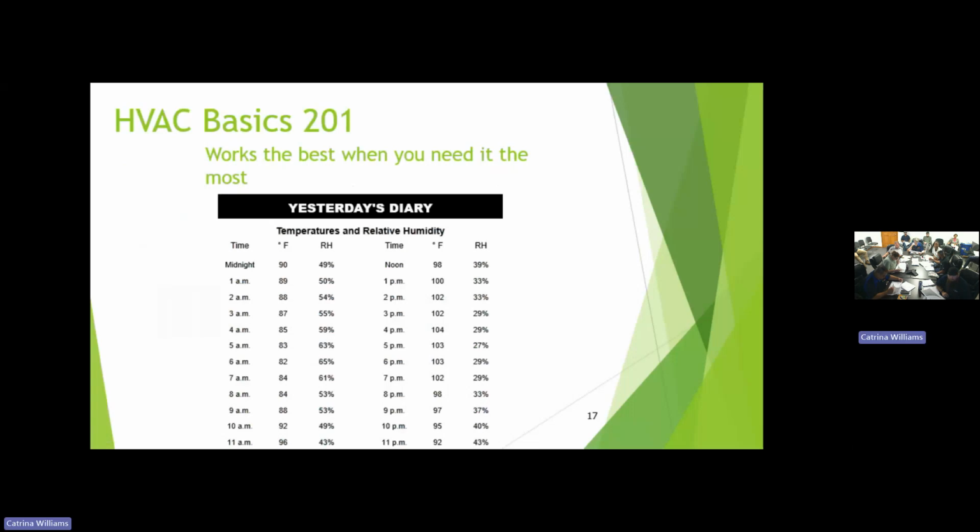Okay, so with that in mind, we'll fill in the formula now. At 82 degrees coming in, 73 wet bulb, with a 9-degree depression, 0.87 times 9 degrees is 7.83, almost 8 degrees. So 82 minus 8, you have a leaving air of 74 that you'd have at 6 a.m. Didn't cool it that much, but you dropped it a couple degrees at 6 a.m. in the morning.